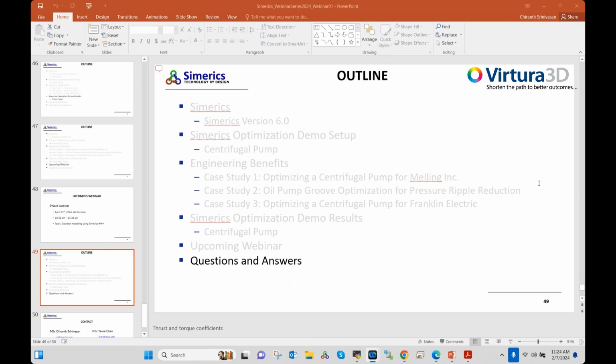From Daniel, you have shown comparisons between cavitation and erosion damages at the valve plate with your simulations. Which quantity do you use to localize the erosion in your simulation? How do you predict the erosion intensity? Actually, there are two points to this answer. One is that in our cavitation model outputs, we have terms which can visualize the power.